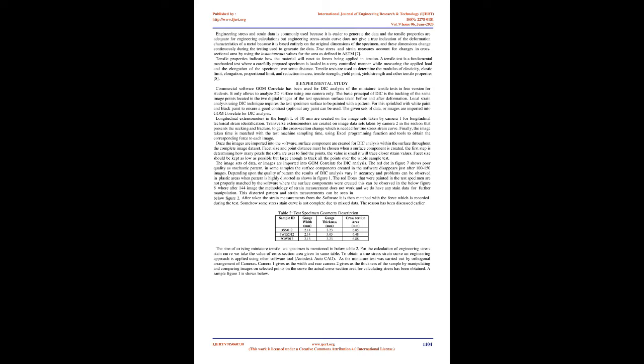Table 1, steel grades available in market. 6. Standard steel grade. EN 10025-2, non-alloy structural steel S275, S355. EN 10025-3, normalized rolled weldable fine grain structural steels S275, S355, S420, S460.